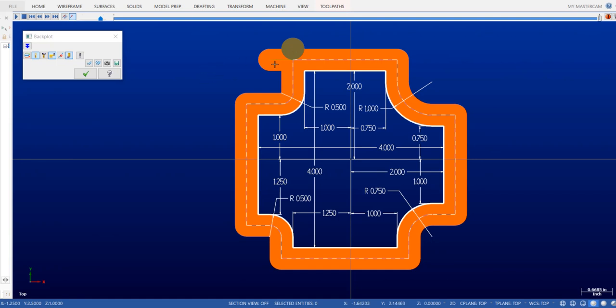So we're going to replace that tangent entry and that tangent exit with a perpendicular move, and during that perpendicular move, as we approach our toolpath, we're going to activate cutter comp, and on the last move we're going to add a perpendicular move to cancel cutter comp.